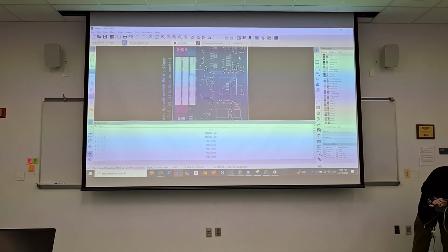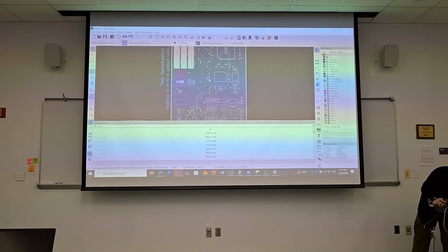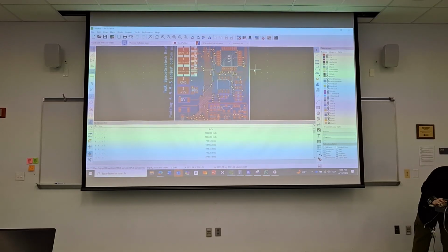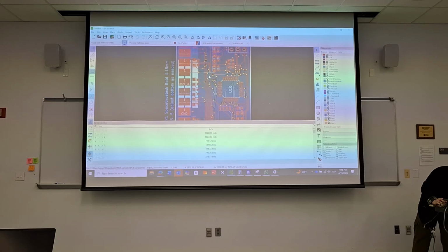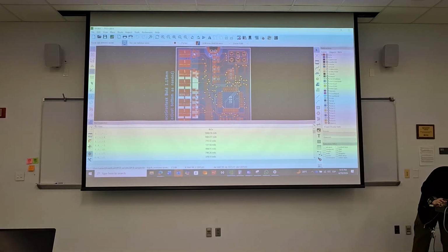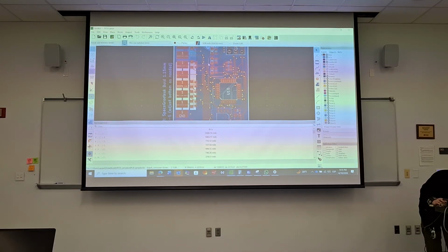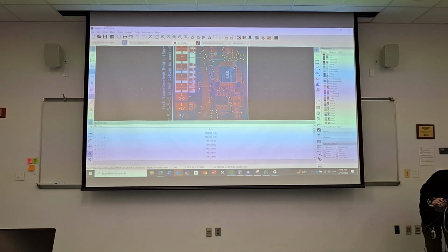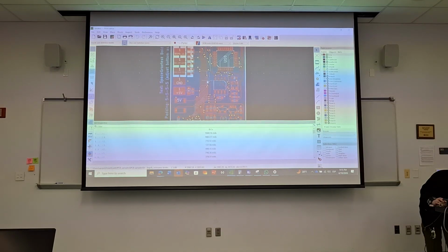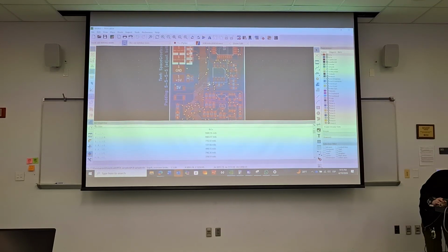This actually terminates there or there. So really I only have two ways for the current to flow. If I turn on this, so if I'm looking at this shutdown sense, its return current essentially has to go out, find its way back in, then go back out, following the ground voids, then back out, follow this ground void, go into this ground, etc.